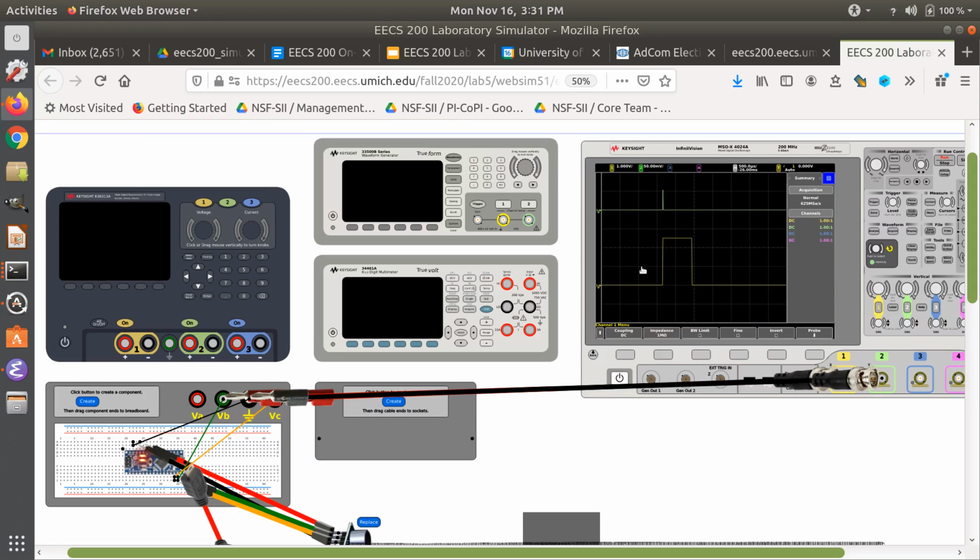And then the yellow trace, which is basically a pulse that is called echo, and it turns on the moment the trigger is sent and turns off the moment a response is sensed from some obstruction. And so the length of this pulse is related to the time it takes for the signal to go out, hit the obstruction, and come back again. And so it's related to that distance.